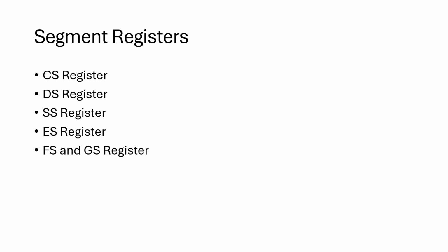The SS register is used for implementing the stack in memory. The system stores the starting address of a program's stack segment in the SS register. So this segment address plus an offset value in the stack pointer, the SP register, indicates the current word in the stack being addressed.